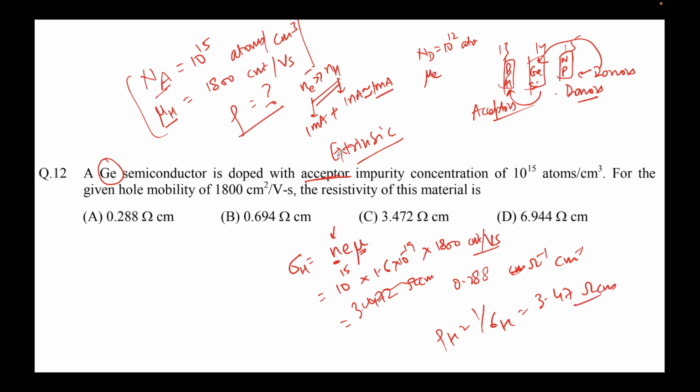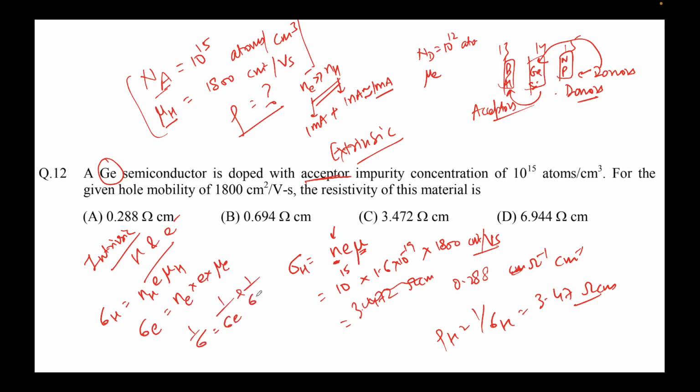We've already discussed the theory. If you have any doubt, ask. Now, if it's an intrinsic semiconductor, we have both holes and electrons. So there I write sigma h equal to nh e mu h, and sigma e equal to ne times electronic charge times mu e. So total conductivity would be simply sigma h plus sigma e. It's like this. See, the smaller one will dominate.